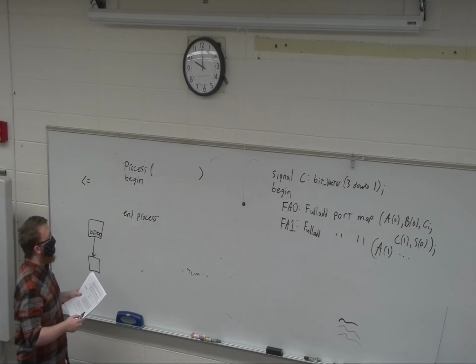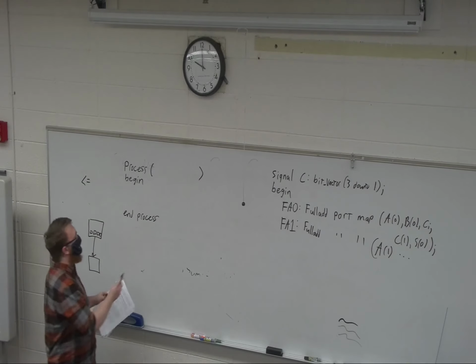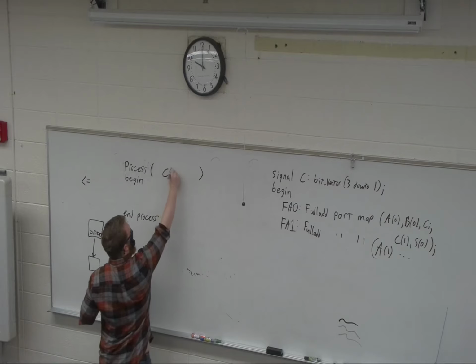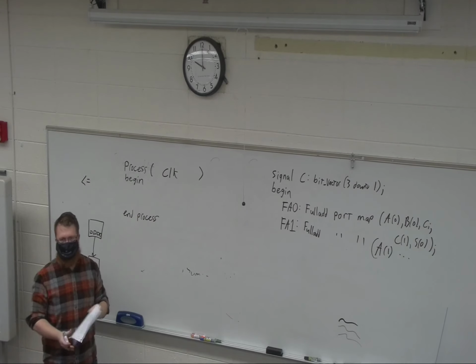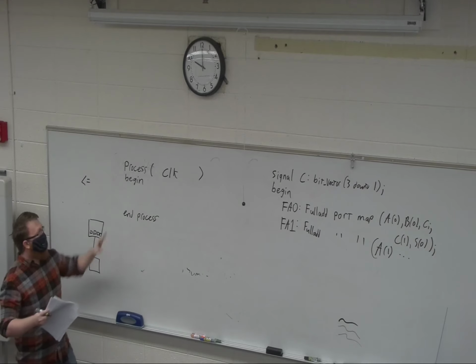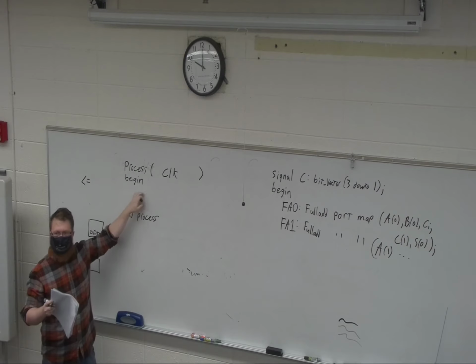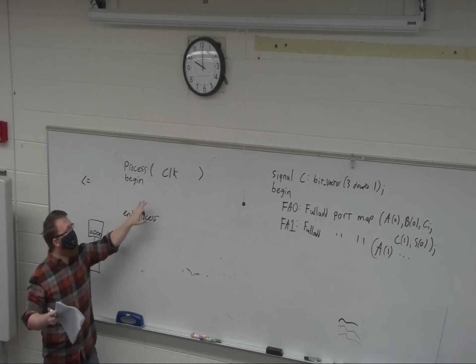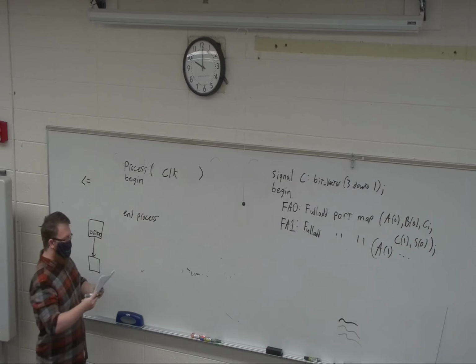So what you'll often do then, if I'm not doing combinational logic, right, if I'm doing sequential, then I'm going to say process clock. And I will almost always use CLK for the clock, right? And that means every time the clock happens, the sensitivity list reacts. But there's an issue with this, right? Because I said that the process happens every time it changes. So is this positive or negative edge triggered? Both. So that's a little bit of a problem.